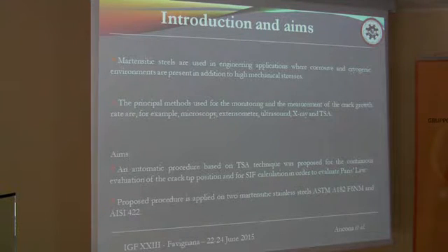In this work, we want to propose a new technique, a new procedure based on the TSA technique for the continuous evaluation of the crack propagation and also the stress intensity factor calculation. So, in order to evaluate the Paris law, we propose this procedure on these two martensitic steels.